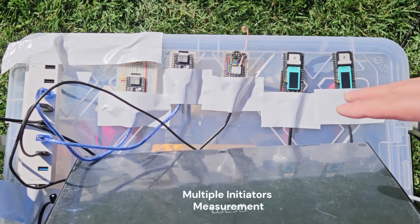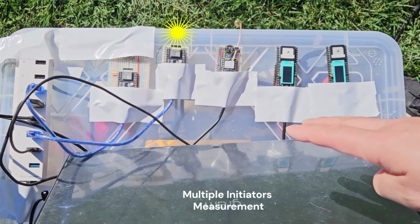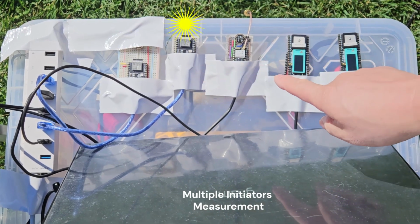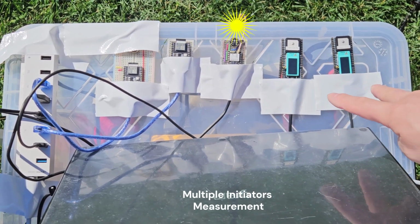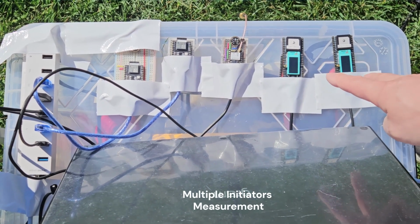Now, let me show you the outdoor experiment. In this test, I used 5 initiators connected to my notebook and 1 standalone responder. For initiators, I programmed 2 ESP32-C3 DevKit-M1 boards, 2 Heltec ESP32-S3 Wireless Tracker boards, and 1 Xiao ESP32-C6.